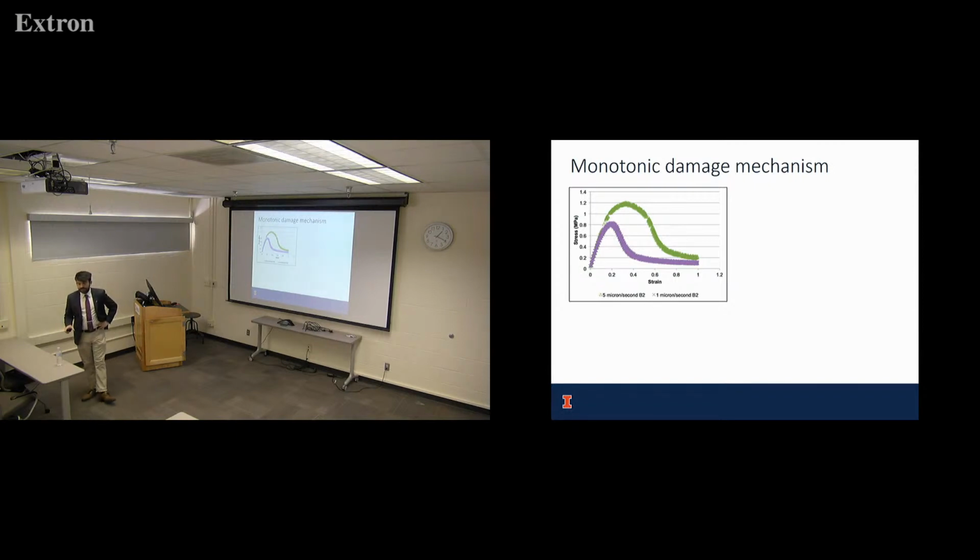That was part of a work that was done at my master's. That was done with the stress control test instead of strain control. At the time, we had been suggested to do stress control by a colleague, who it turns out later, it wasn't a good idea. But basically, he told us to do stress controlled instead of strain controlled. Yeah. So we applied a rate like 1 Newton per second instead of 1 micron per second or what it was.